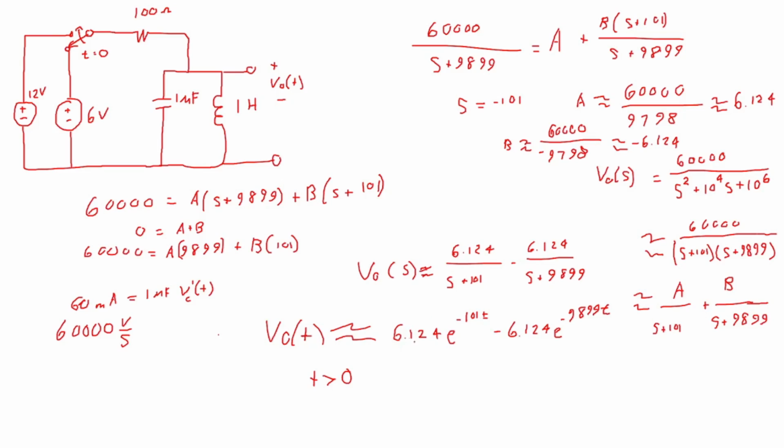And in an overdamped situation, the more overdamped it is, the smaller, or the slower, this term becomes. And this slow term means that the discharging process, the resonance here, is being very heavily damped by this resistor. And so the capacitor charges very quickly, but then it has to discharge slowly.